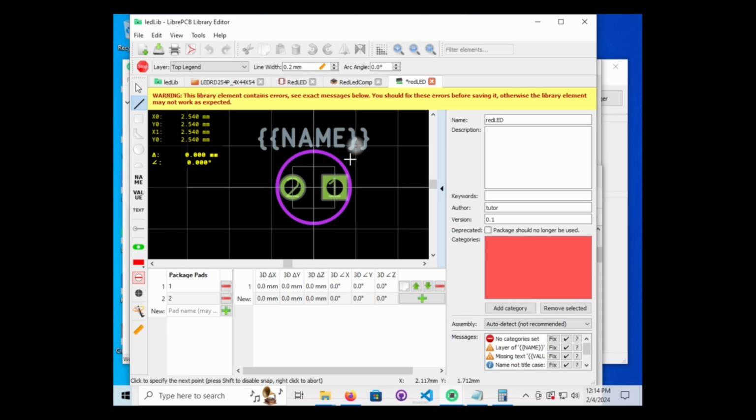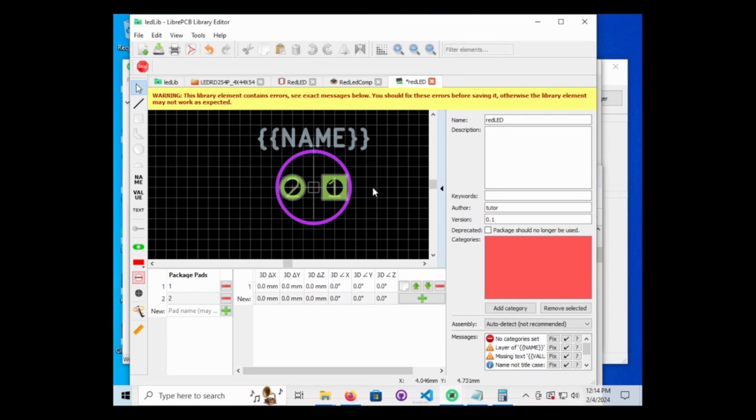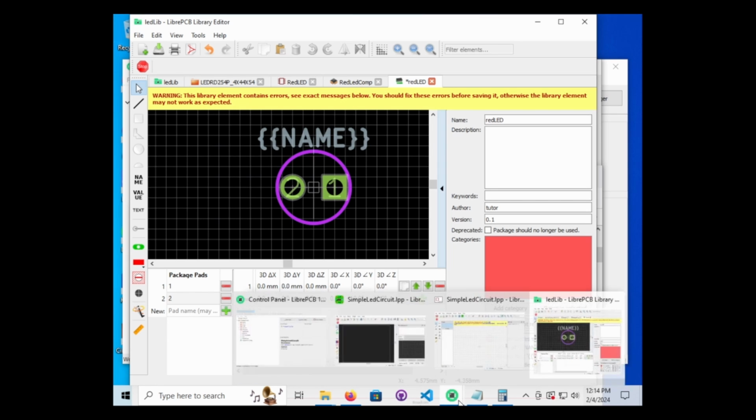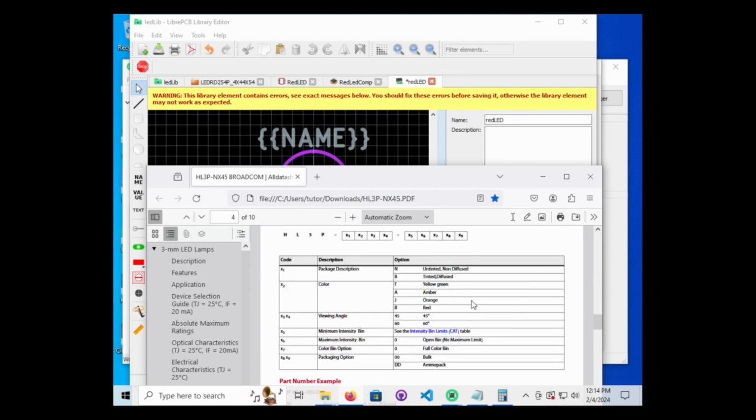Alright, I think we're gonna go ahead, change the grid real quick. Let's do 0.635, and we're gonna double check. Sorry, I'm double checking my pitch is 2.54. Okay, we're good there. I'm gonna go ahead and add a negative.